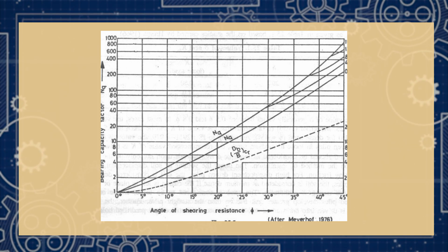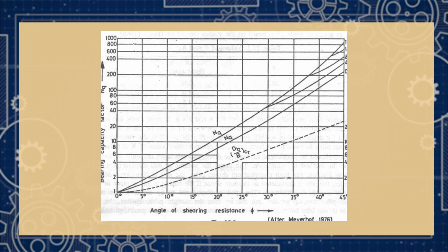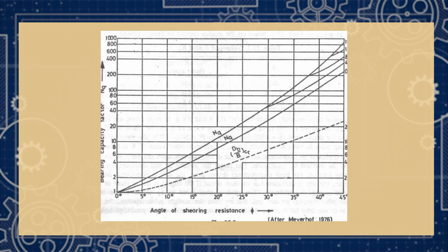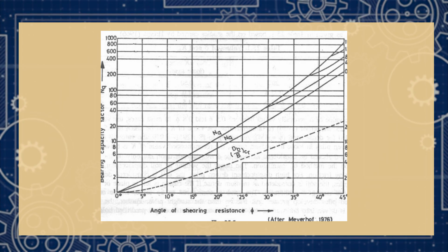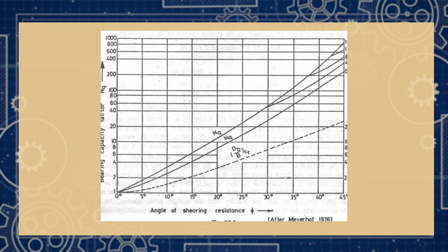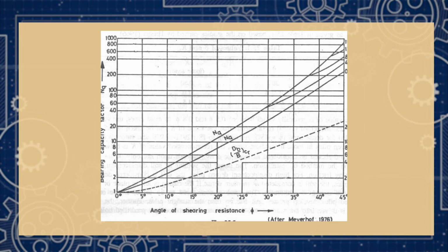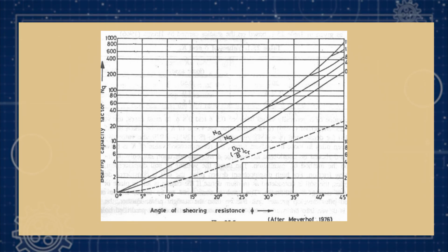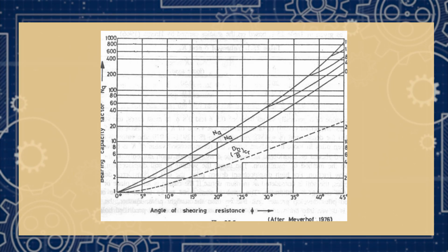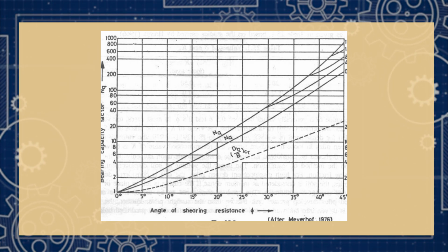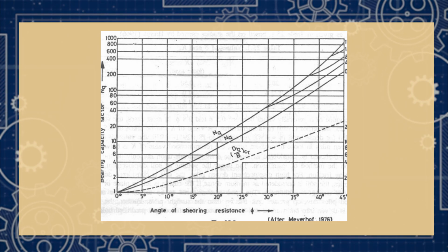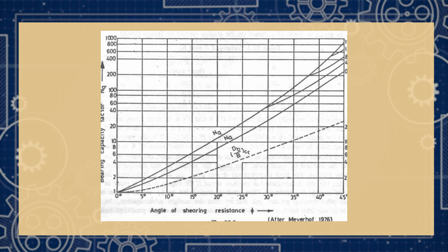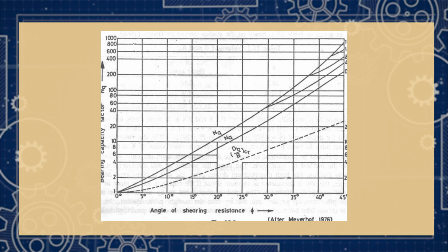Each soil has a different friction angle. After conducting the laboratory test, you get the friction angle. For that friction angle, you can take the Nq value for the respective depth. You can see from 5 degree, 10, 15, 20, 25, 30, 35, 40, 45. You can see the Nq value is there, and D by B is also there.